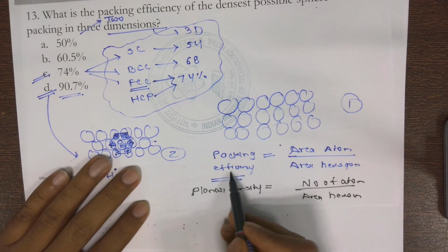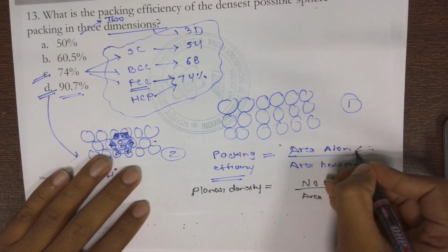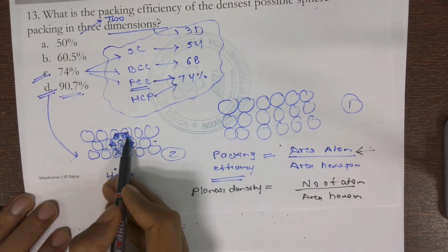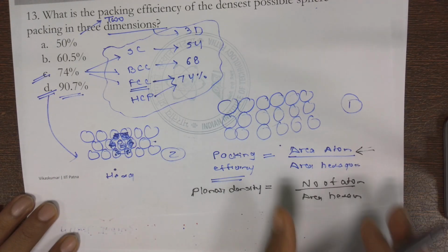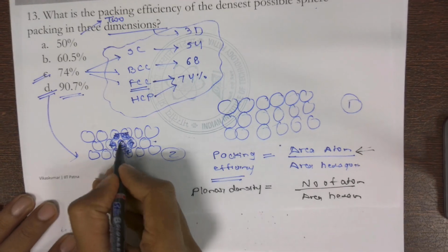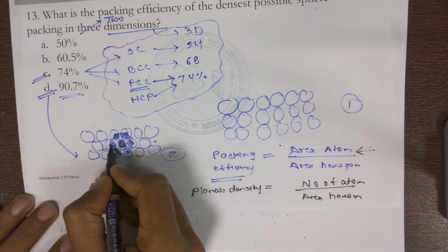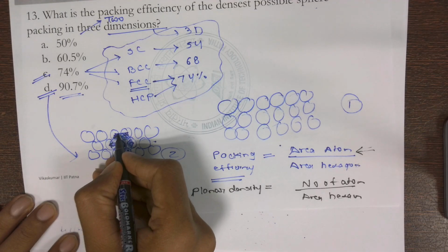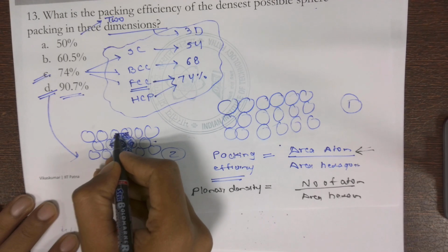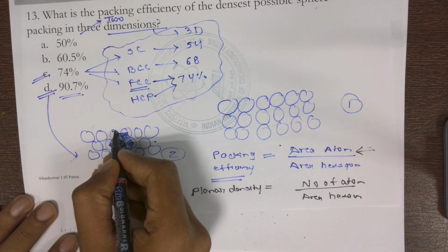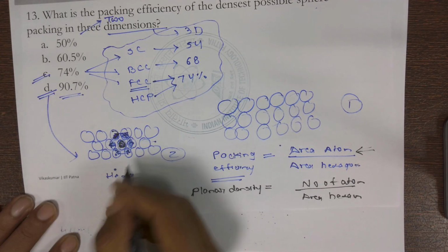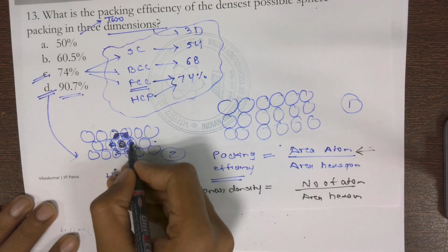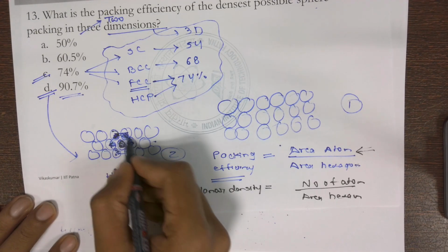Here, when we are talking about the packing efficiency, we were telling that it will be the area of the atom which is occupied. Here we have to say the number of atoms that are there effectively. So one atom will contribute to a certain extent, like this angle is 120 degrees. So this will contribute 1/3, because the remaining 120 will go to the different hexagon. So effectively 3 of them will make 360 degrees, and they will contribute entirely 1.